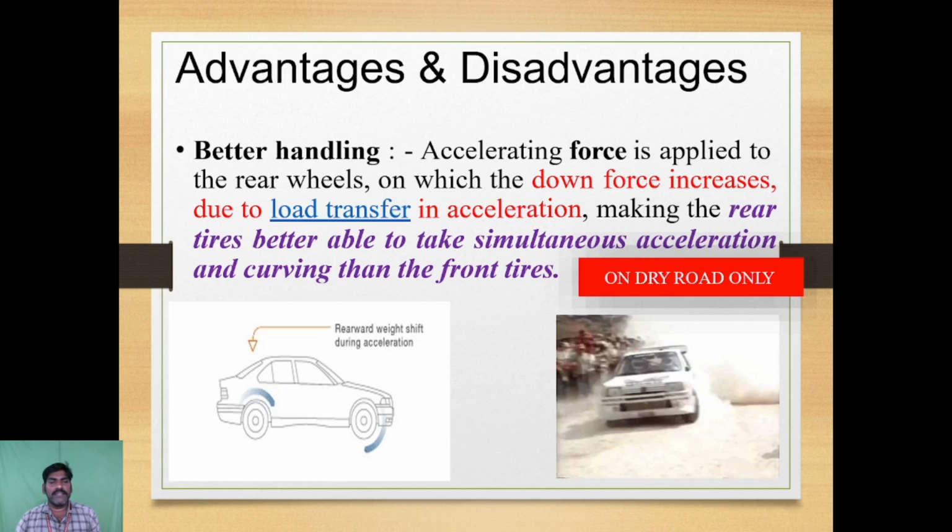Advantages and disadvantages. Better handling. Accelerating force is applied to the rear wheels, on which the down force increases due to load transfer in acceleration, making the rear tires better able to handle simultaneous acceleration and cornering than the front tires.